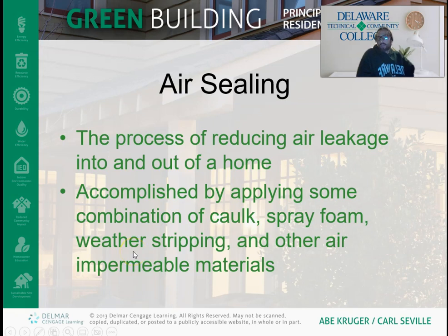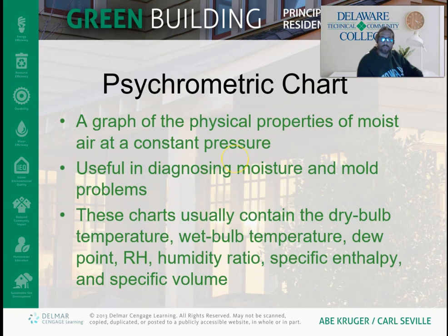If you're building a brand new building, you want to make it really tight. We'll actually talk about passive design standards, which are so tight that you have to bring in fresh air all the time. But most buildings are leaky enough that residential buildings generally get enough fresh air. We'll talk about some trouble spots where air commonly leaks in and out of buildings, and how you fix that. So we'll address that this week.